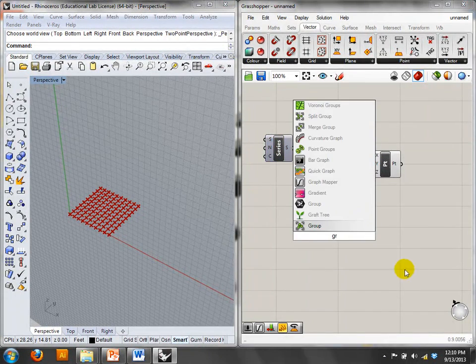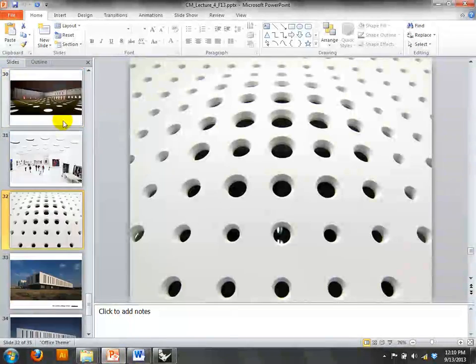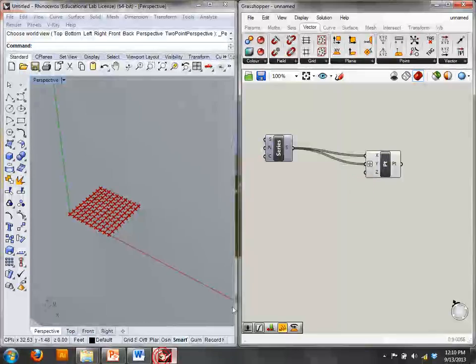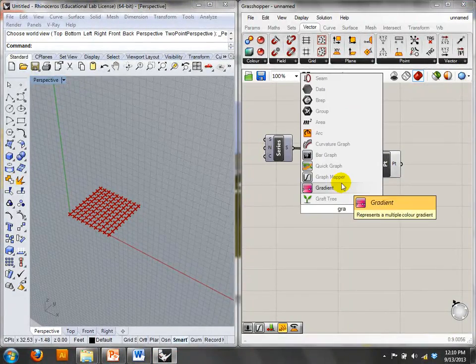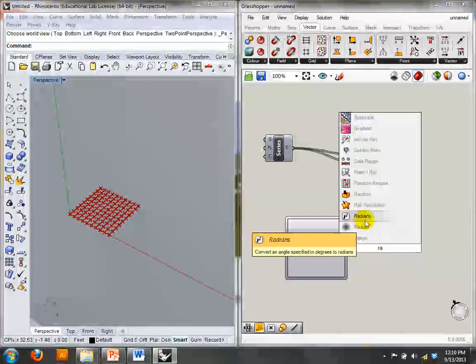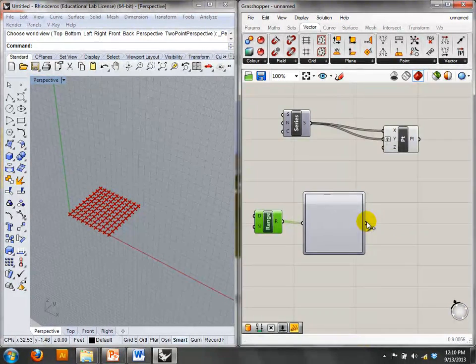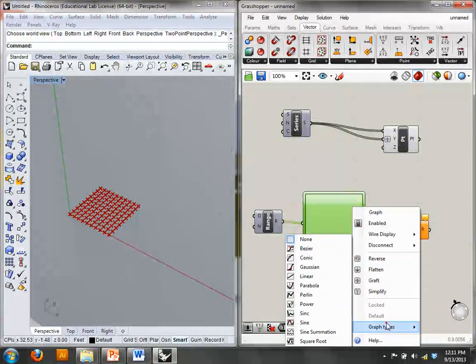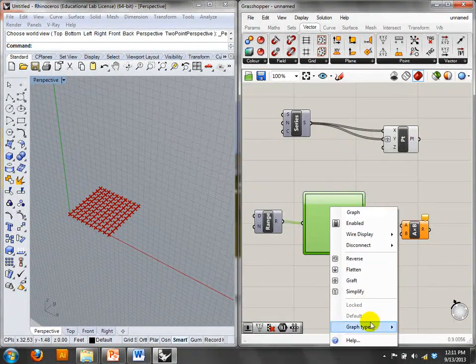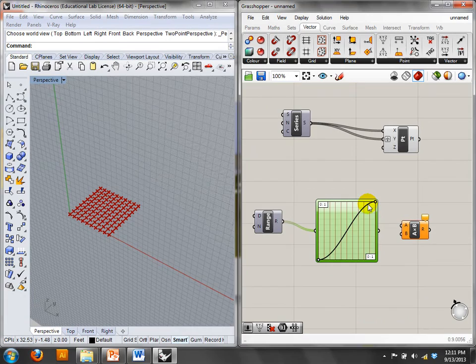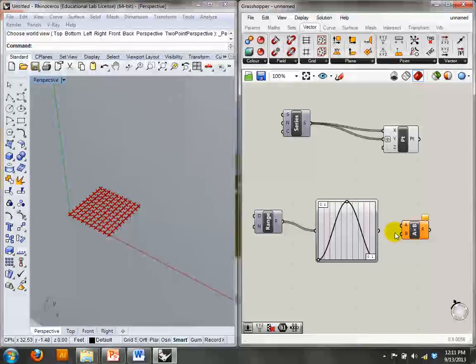And the thing that I really want to mess with is the z-coordinate. So what I'm trying to do is recreate this kind of shape, this kind of bulge. And we actually know how to do that. So I'll do graph mapper and range. And this is another pattern, like if you want these kind of hyperbolic shapes, basically you can start with something like a parabola, or you could do a sine wave. And I just like to make it a hump, okay?